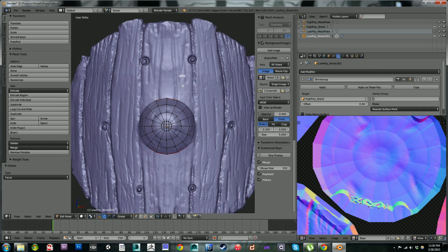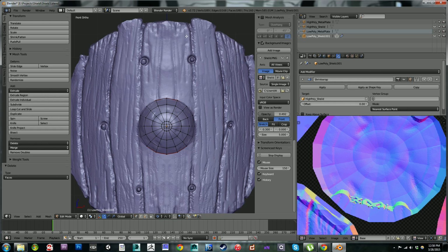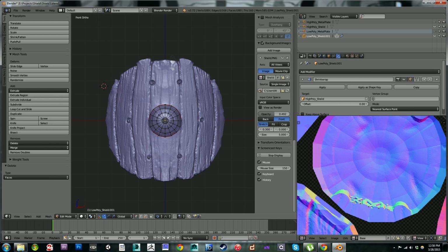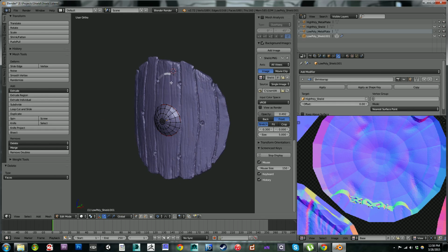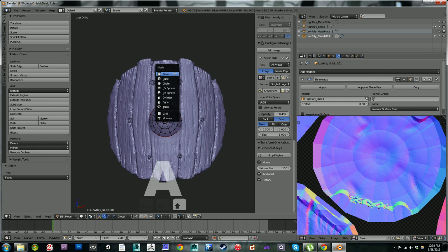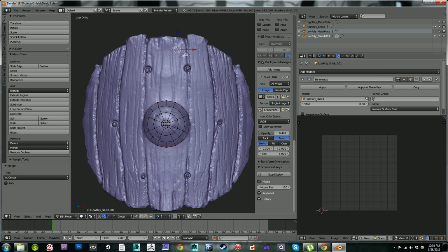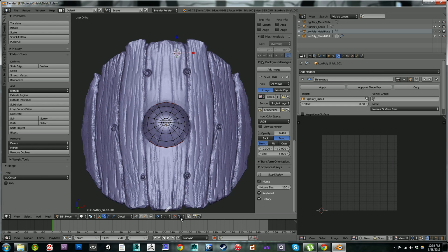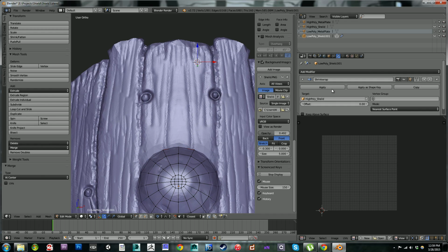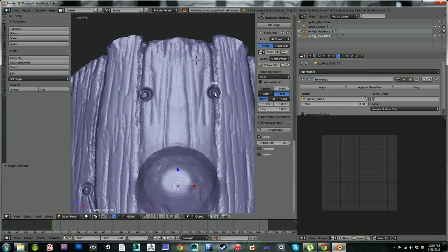And what we will do is we'll use snapping. Let's go into orthographic and set our 3D cursor right there. Just add like a cube or something, and then bring all of those verts to the center. And now what we're going to want to do is use face snapping. And I'm going to apply the shrink wrap.